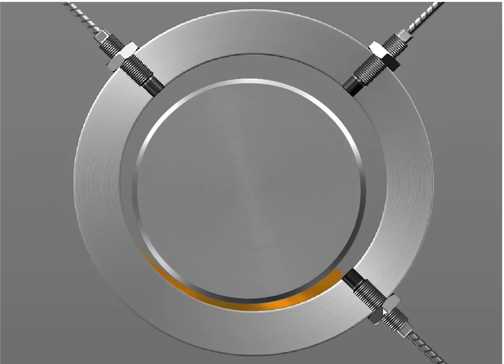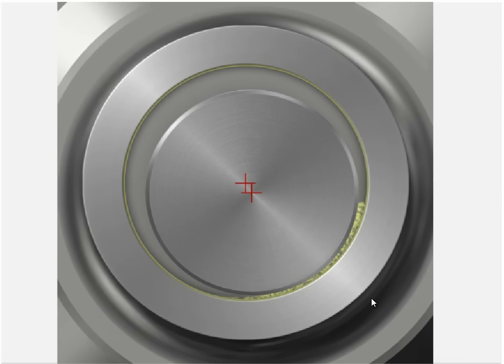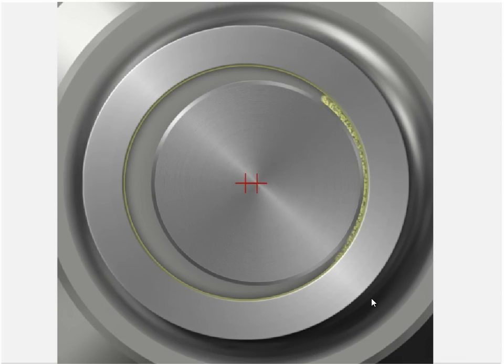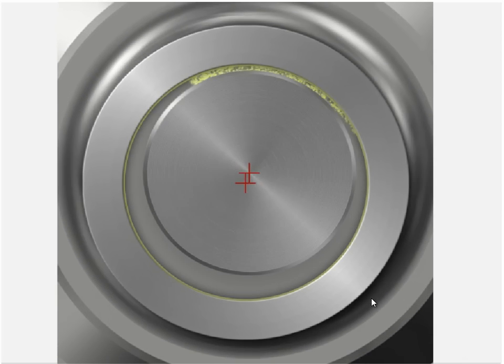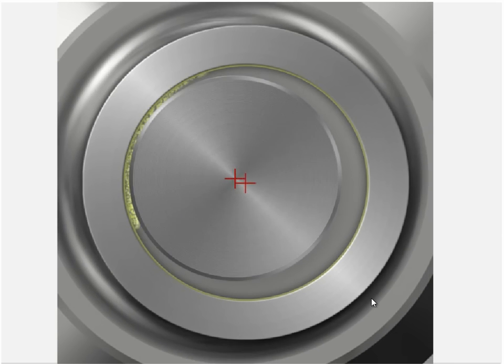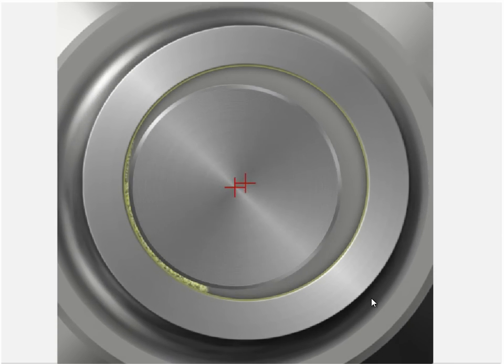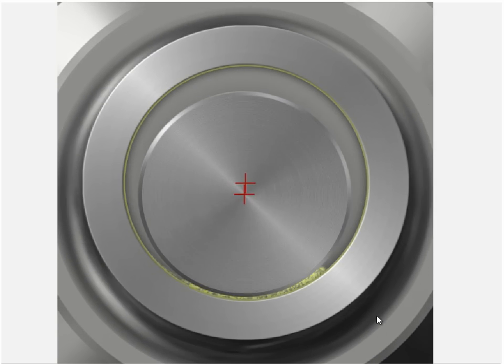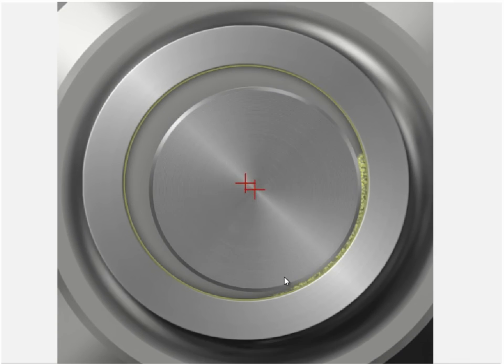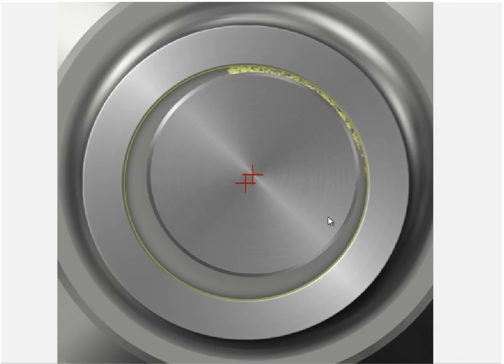The third probe here is not in the same plane as these ones. This one might be at the end of the rotor or somewhere where there's a key or keyway, and it measures that displacement, and that gives us our once per revolution information. What we'd like to be able to tell is just what is the rotor doing, what is the journal doing within that bearing. In this instance, we have oil whirl. This wedge of oil is actually following the shaft around as it moves in this big wide motion.